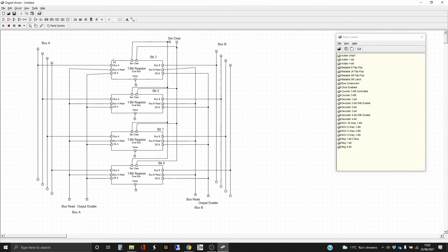Right, I think I'm done. I'm just going to do a quick visual check round that everything seems to be connected as it should be. So the first check I'm going to do is to check that every pin on these 4 registers is connected. So that's just looking visually around in a circle to check that, and they seem fine. And I wouldn't normally draw it with my mouse. I don't necessarily need to do that for the visual thing, but this is to help you see what I'm doing. Okay, and then I'm going to look at the various inputs and see that they're connected.